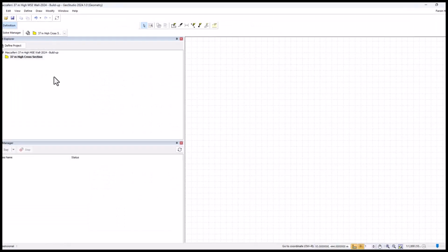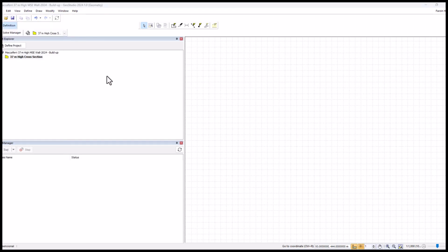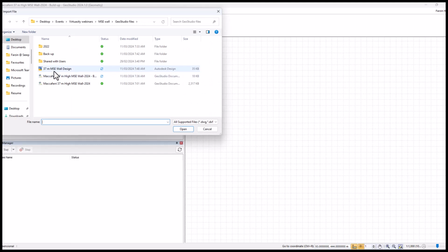This is the model that I created for a build-up, the same model that we have available online. So you can actually download this model and see it online, available with a PDF guide. But I'm going to create this model step by step. First, you need to import that geometry which we earlier showed you in a CAD file. Simply click on File and then move to Import. Once you are in Import, you can see the geometry is created here.